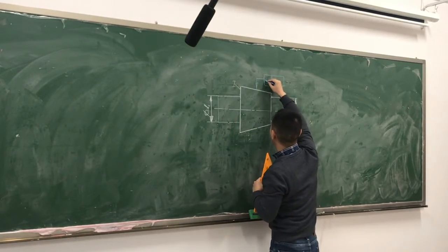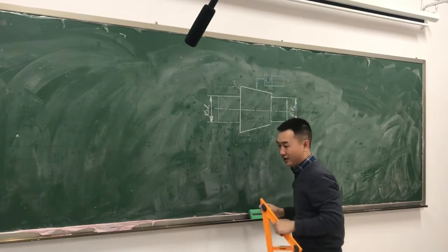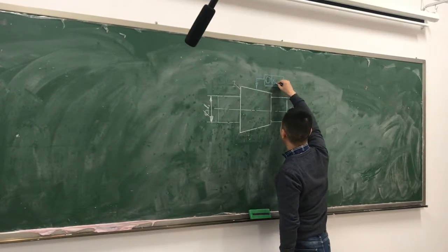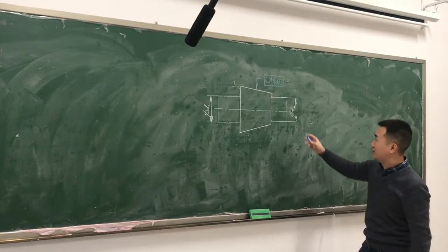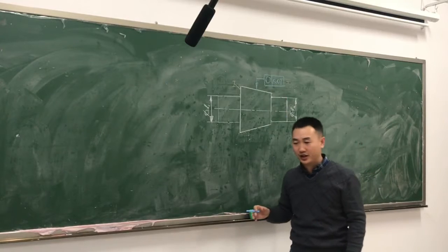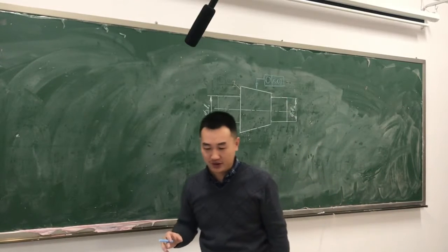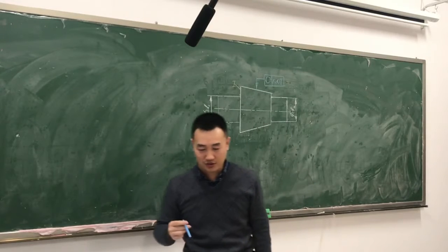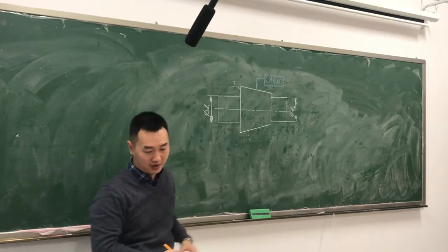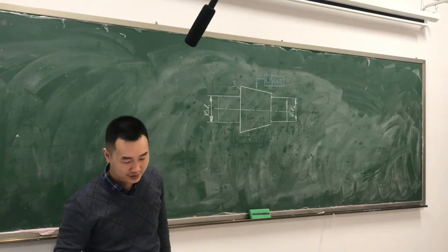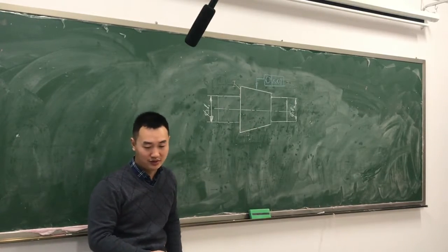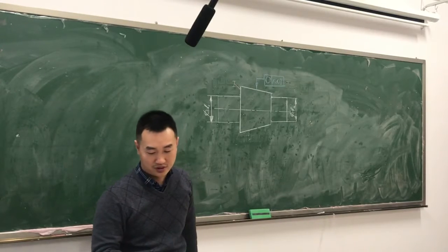The symbol is the circle, right? And next, we write down the tolerance value, 0.01. And here, as I have stated, for circularity, we do not need the phi, because the tolerance zone is the space between two concentric circles. So here we finish the first one, and the next one is the circular cone. Also for the circular cone, the line straightness is 0.02.